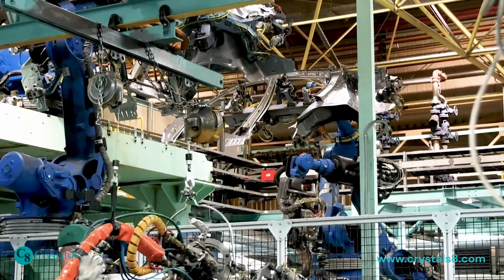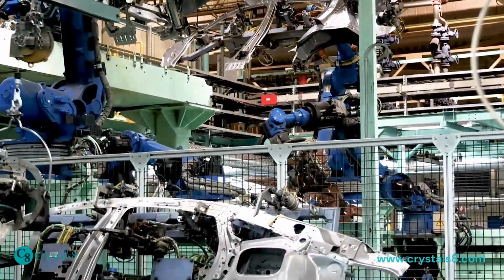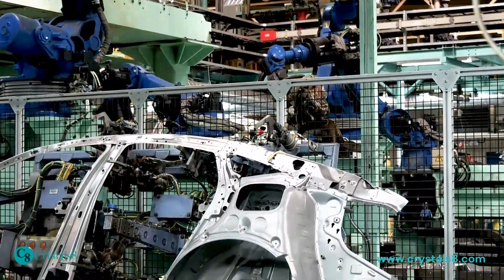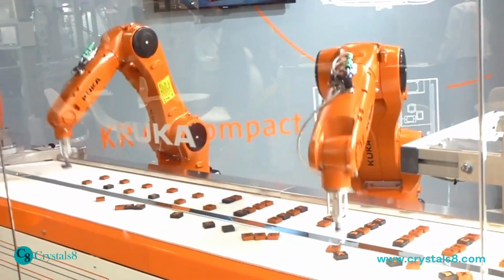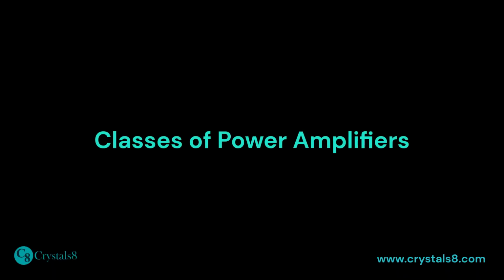DC power amplifiers. DC power amplifiers are industrially used to amplify a PWM signal. These are typically used in electronic control systems which require high power signals to drive electrical instruments. The feedback from microcontrollers is amplified and fed into DC motors or actuators. There are several classes of power amplifiers, but we can mostly see Class A, B, and AB power amplifiers in applications we use in our day-to-day life.